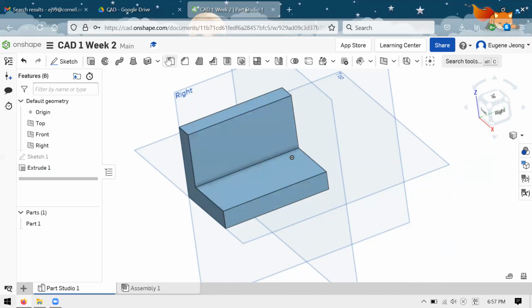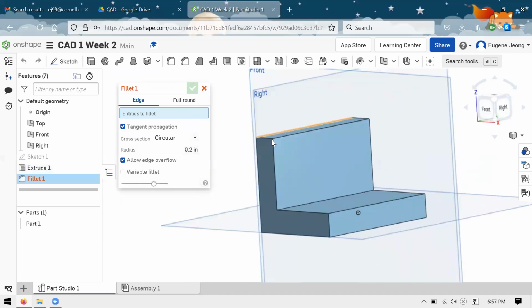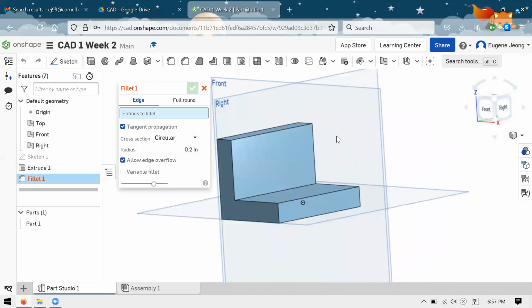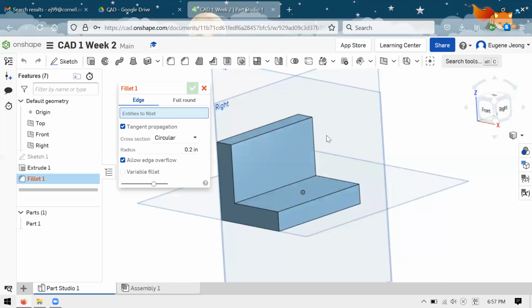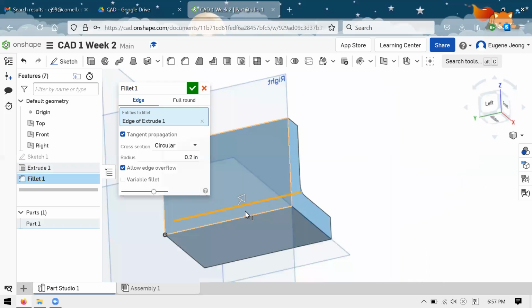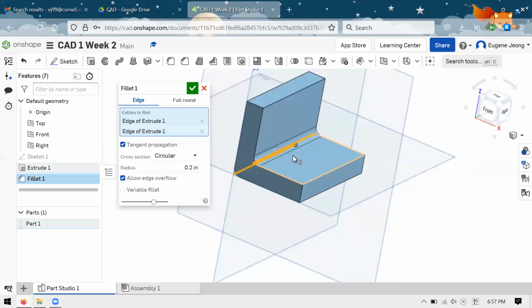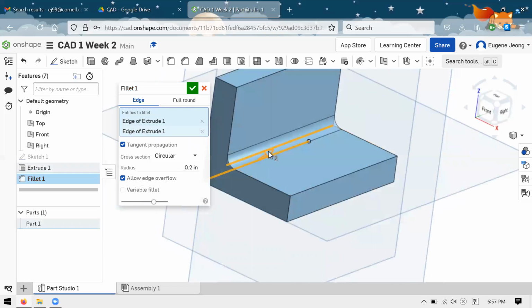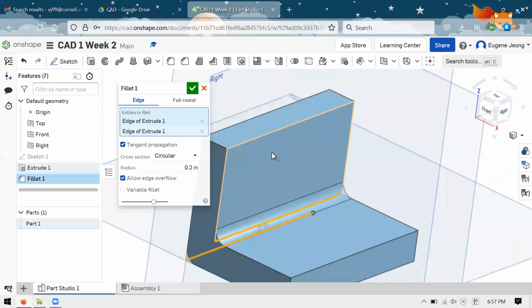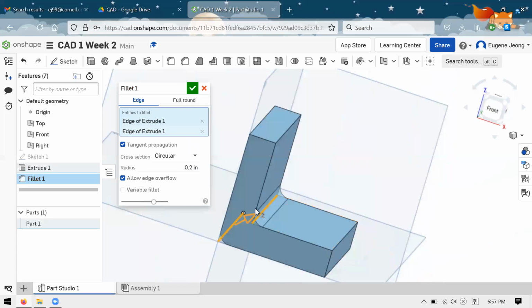And so there's a couple things to point out about this. The first reason is, why would you do this? And there's a few reasons. The first is that sometimes when you use it well, it can look more aesthetically pleasing, which is always nice. The second might be that when you fillet something, you're more accurately representing how it's going to be manufactured.